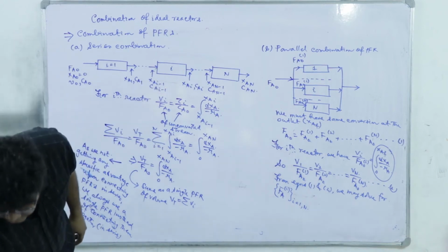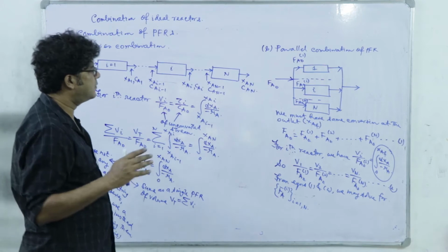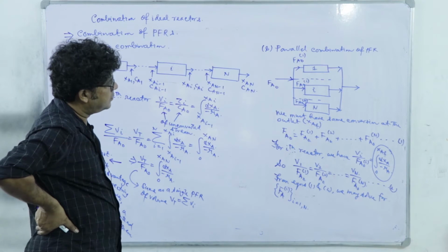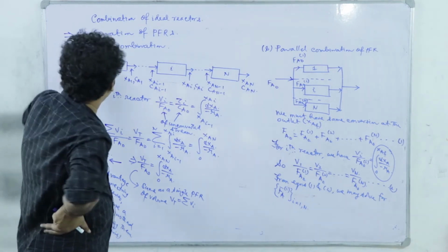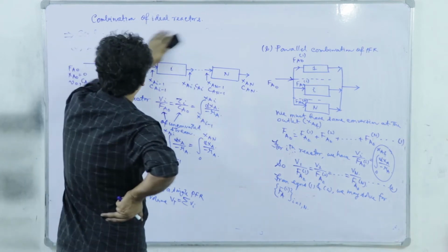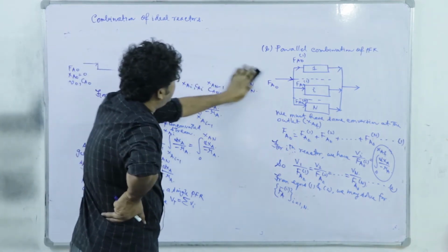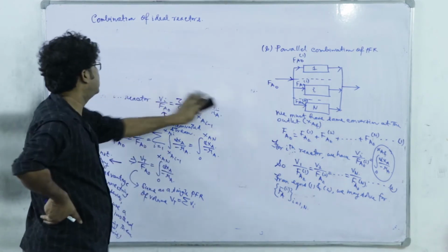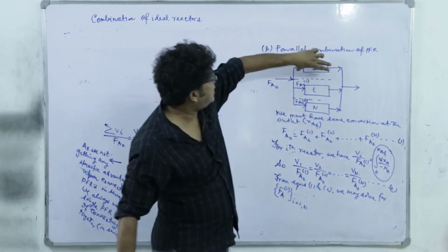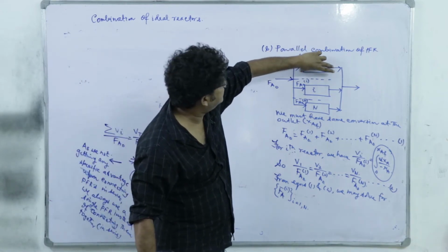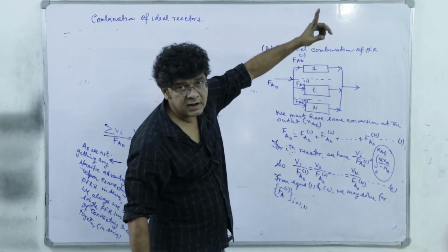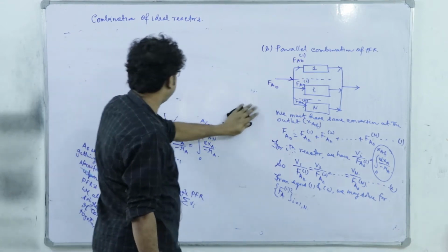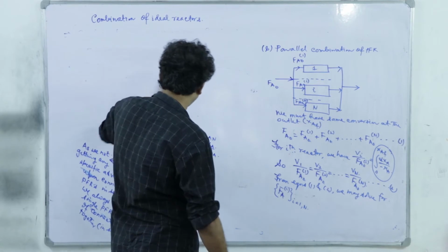So, that is the underlying rationale behind using the PFRs in series, right. Now, if I have a series-parallel combination of PFR, we are not going to discuss it separately. So, you see that if I have 5 or 6 PFRs in series, we can actually replace it by a single larger PFR and we can apply the same formula on this combined PFR in each of these parallel streams, right.